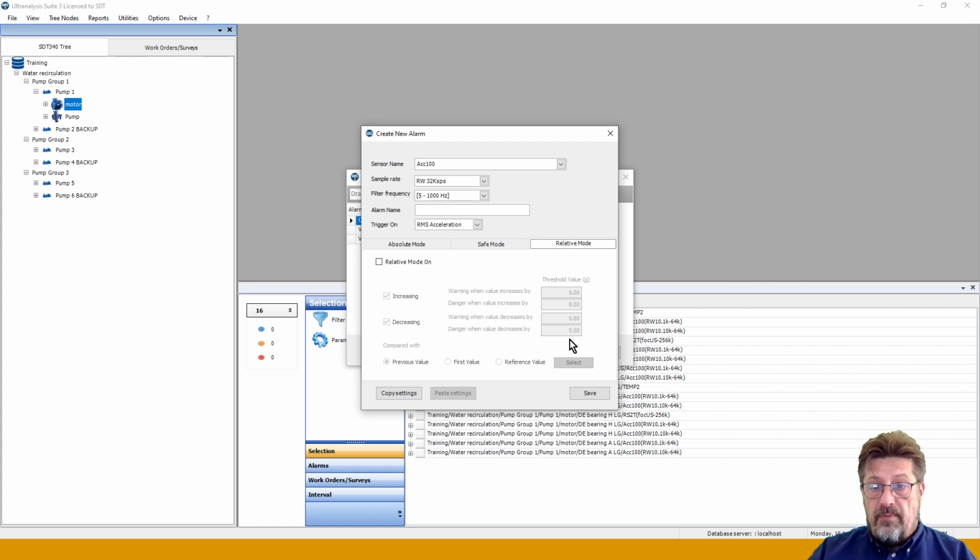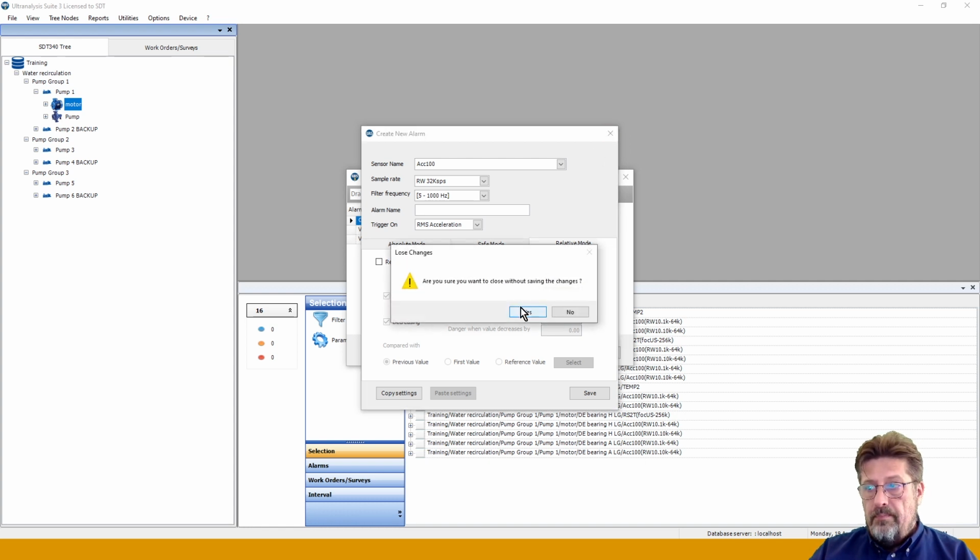Multiply that by 4 indicators, and you will see that it's a big number of eyes monitoring each point. You just have to set them properly. I'm talking about numbers. So look at the data, understand what is good and what is bad, see how consistent your data is. The more consistent the data is, the more sensitive alarm you can put. And this is the way you put alarms.